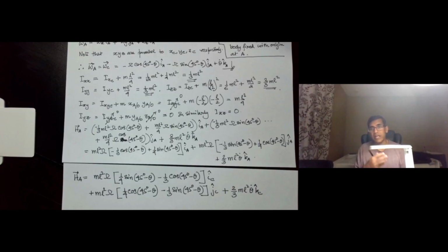It does not consist of any product of inertia terms, but then we have to move that angular momentum to the point A using that r cross mv term, which basically computes the angular momentum of the center of mass itself due to its velocity about the point A. So that introduces an extra term, but otherwise the two methods are equivalent, as we see here, and they give the same answer provided we use the same unit vectors or parallel unit vectors, which was the case in this problem. So that's it. Thank you so much.